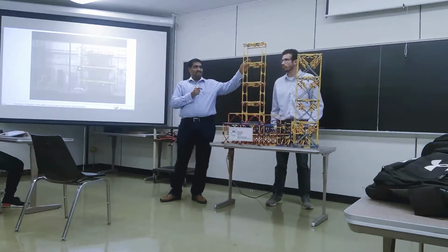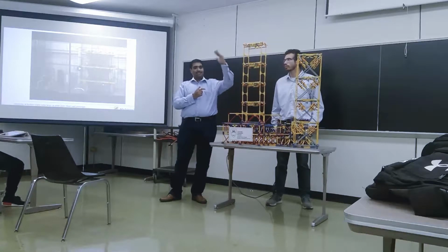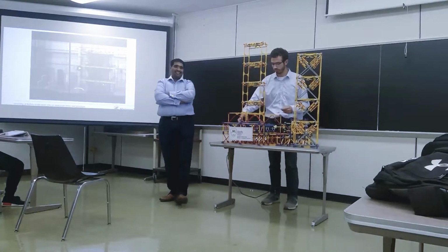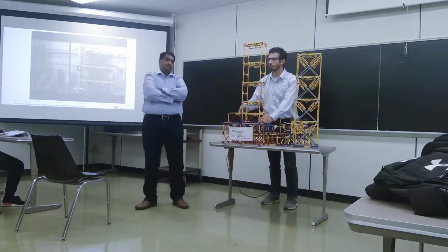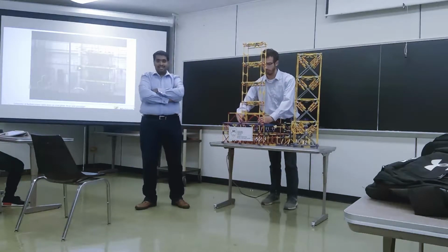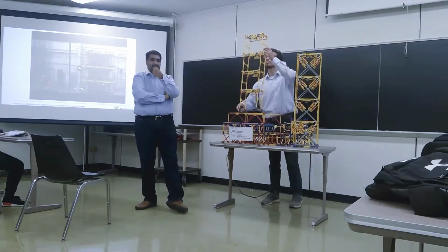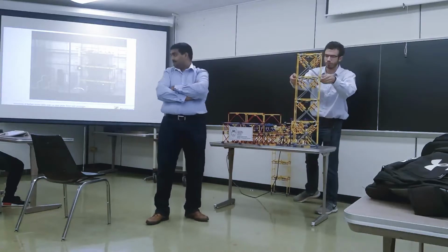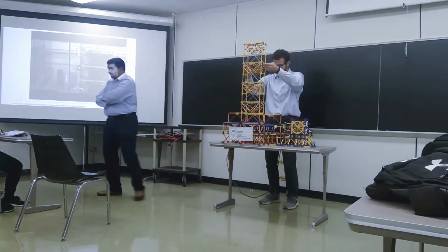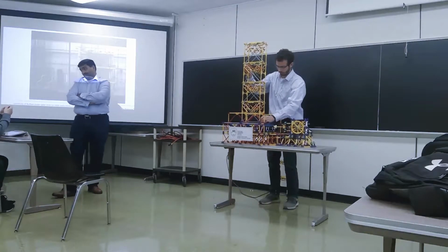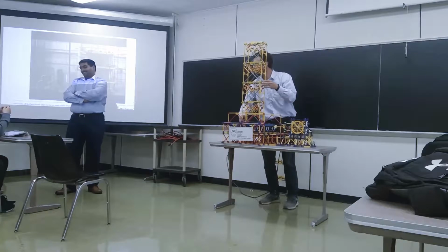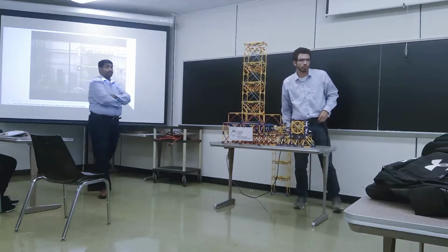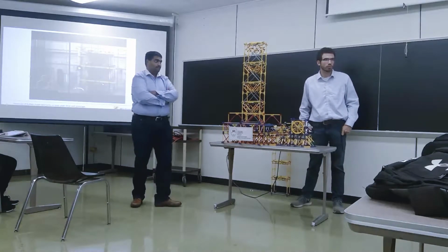And the other thing is, you guys are not even considering degrees of freedom swaying this way or twisting. So in that case, each node point can have 3 degrees of freedom, at least for this. So we can complicate it by having each node 1 degree of freedom, or we can model it by 3 degrees, and 12 degrees of freedom. We can model it as 12, or we can model it as 3, or we can also model it as just 6. So if you model it as 12, what are the 3 degrees of freedom at each floor?